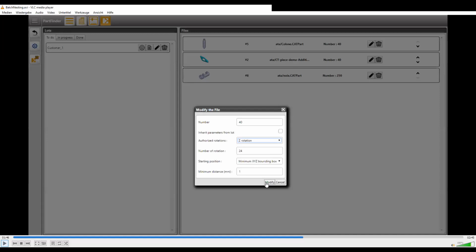So it's not only global parameters that are applied, but you can really specify it for every part according to the 3D printer, and also it's really relying on the part, because there are, for example, really dense parts with a high material density, for which you have to define a bigger distance to the other parts, so that you can make sure that inside the machine you don't have any temperature problems.